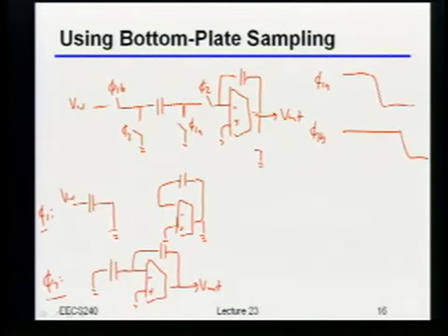So we're kind of kicking our charge injection into our input signal. This is true. So that does mean that whatever is driving that input better have sufficiently low output impedance, right? Now, the good news is that if you're driving it from some other OTA in feedback, that means it should indeed have relatively low output impedance. But you're absolutely right. If I did this with something that had a very sensitive input, you better be careful, because I'm going to be kicking that charge back onto that input, and if that input can't handle it, then when you come back around, you'll again be picking it up. That's a great point.